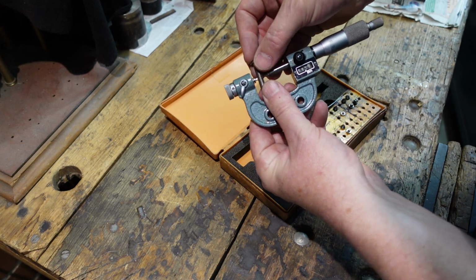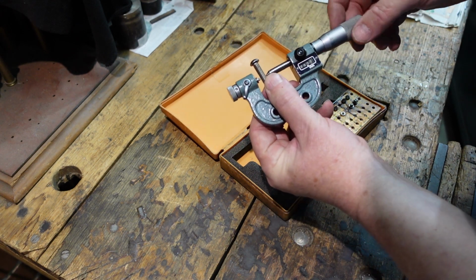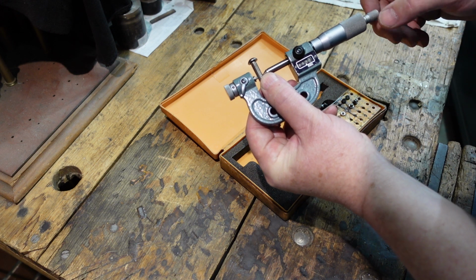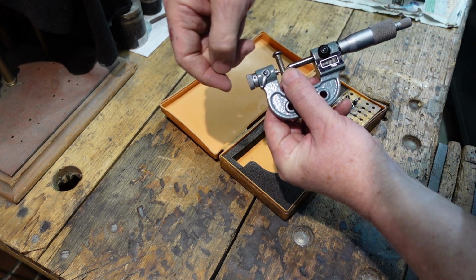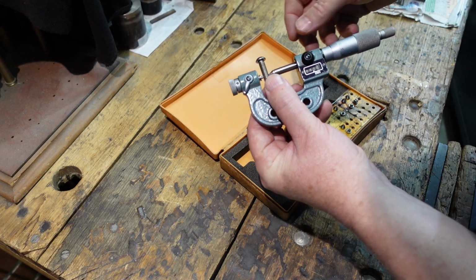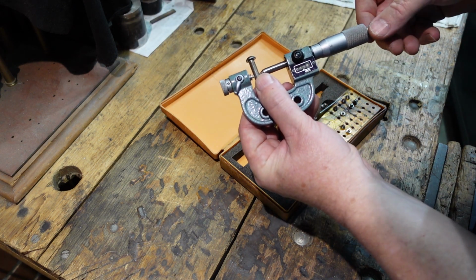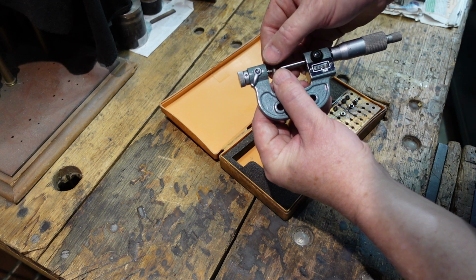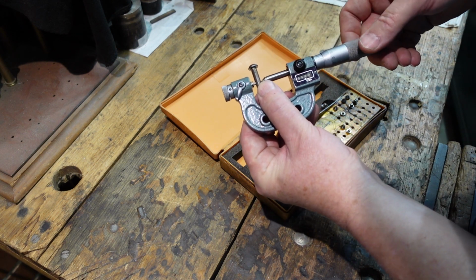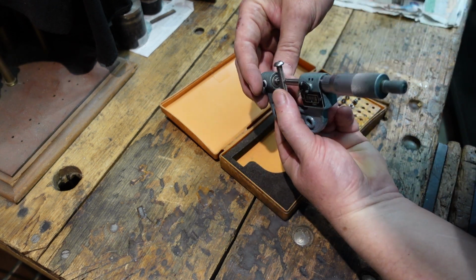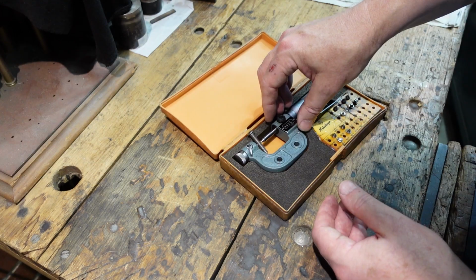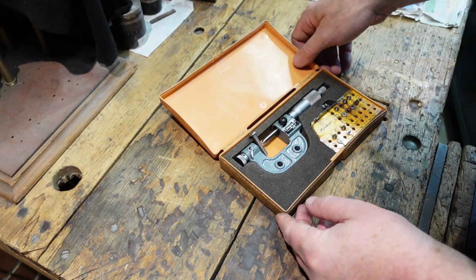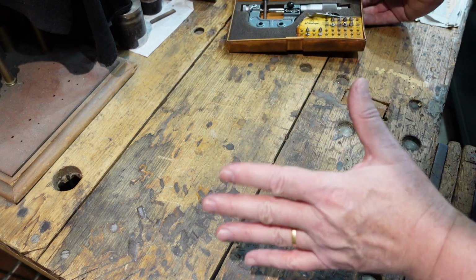So what you're doing is you're getting your thread, and you're putting that in there. The cone goes on one side, the V or the W shape goes on the other side, and so you're measuring across the thread, and the idea is you're measuring to the pitch circle diameter. So you want to be basically diametrically opposite there. How does that relate to the thread itself?